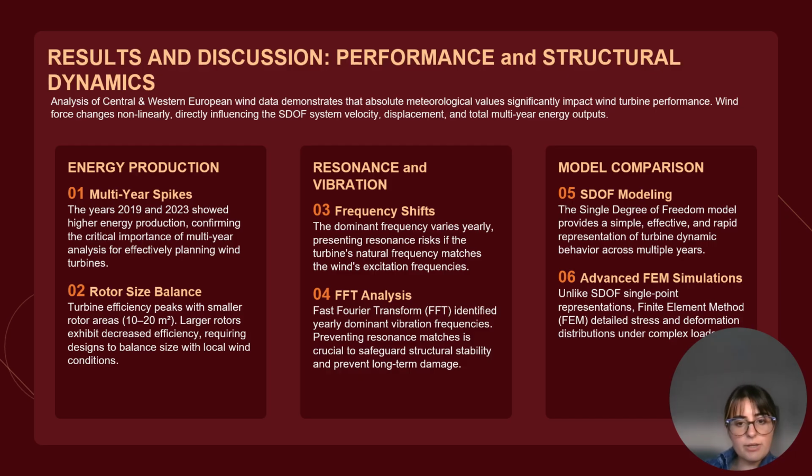Regarding the model comparison, there are two models being compared. The single degree of freedom model provides a simple, effective, and rapid representation of turbine dynamics over multiple years, and the advanced FEM simulations, meaning finite element methods, are detailed for stress and deformation distribution under the more complex loading of the turbines.